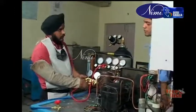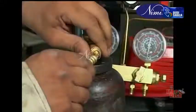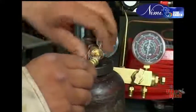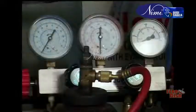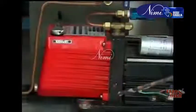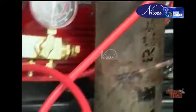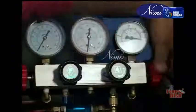Install a rubber charging line on the middle port of the manifold and the other end on the refrigerant cylinder. Cylinder valve remains closed till evacuation. On the third port of the manifold, the HP gauge, install the vacuum pump with the help of another charging line. Open the valves of the manifold and switch on the vacuum pump.